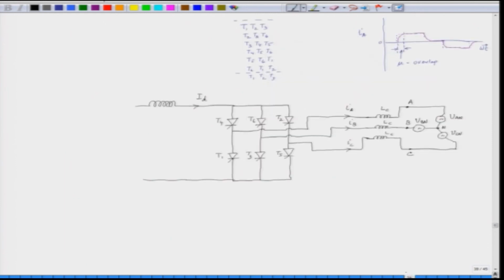So, the DC voltage we are talking about is this DC voltage VD load side. So, this voltage is plus minus. So, this converter is actually operating in the inverting mode. It means the energy is being supplied from the DC to the motor. So, this is the flow of the power P.